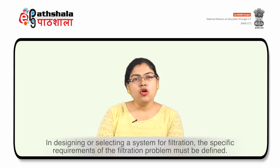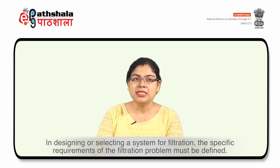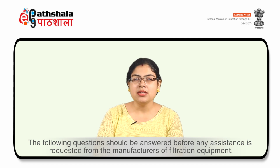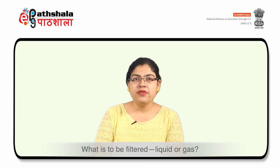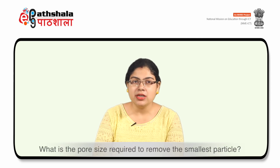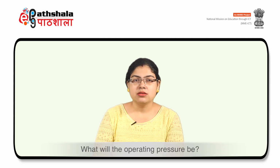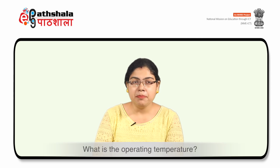Lastly, we will discuss how to select a filter. In designing or selecting a system for filtration, the specific requirements of the filtration problem must be defined. The following questions should be answered before any assistance is required from the manufacturers of filtration equipment. First, what is to be filtered, liquid or gas? What liquid or gas is to be filtered? What is the pore size required to remove the smallest particle? What is the desired flow rate? What will be the operating pressure? What are the inlet and outlet plumbing connections? What is the operating temperature?